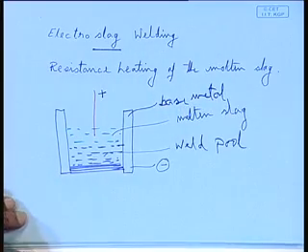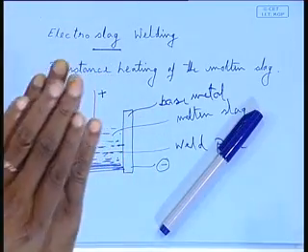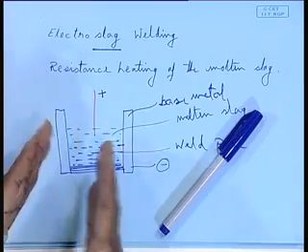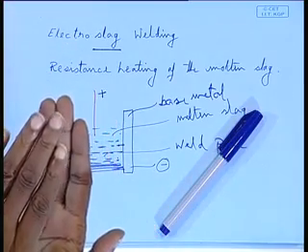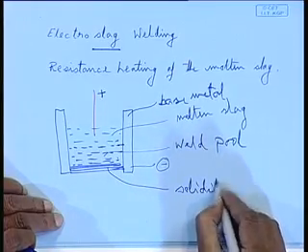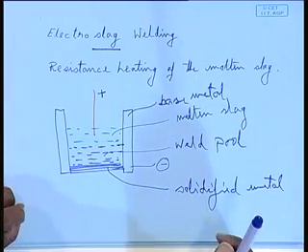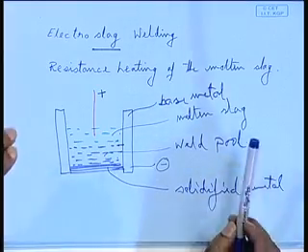So, from this possibly you can figure out that this process is a vertical welding process. The weld metal, the weld pool, molten metal, over that the molten slag is floating. So, it ought to be vertical, right, and this whole thing will keep moving up. As it is moving up, the molten metal gradually gets solidified. That is the solidified metal below. So, electroslag welding is essentially a vertical welding process, wherein the heat is generated from the molten slag, the electrode is melted and gets deposited, and the whole thing keeps moving up.